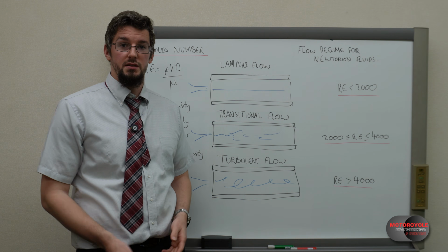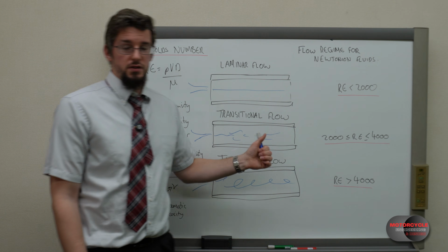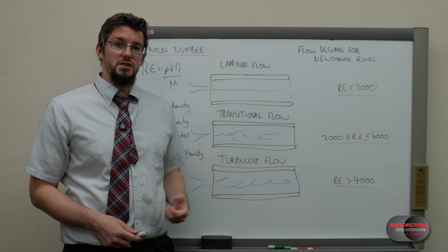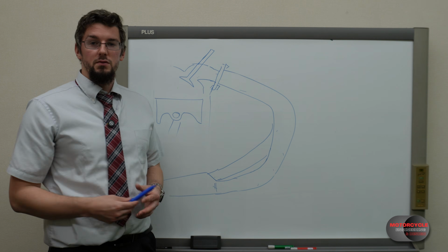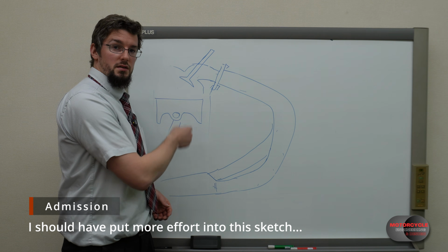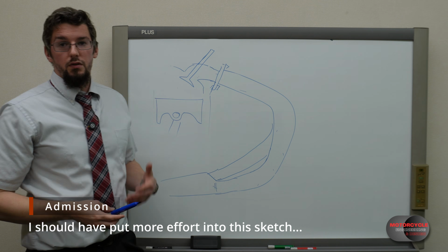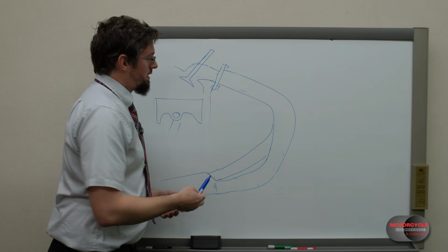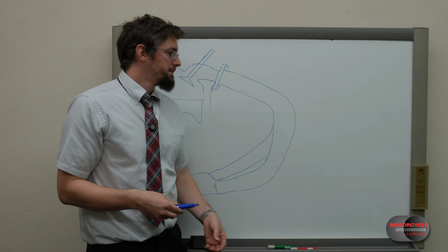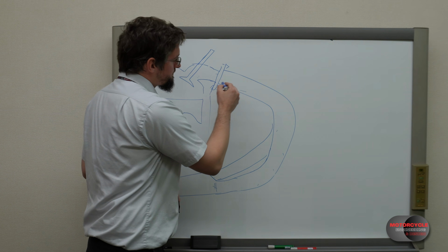So why do we care about this? Essentially, this is our exhaust pipe. Any excessive back pressure that's created from the friction loss is going to be applied to the chamber, preventing the exhaust gases from discharging. So what's actually happening in our exhaust system? Since we actually have a reciprocating piston here, and we have this valve which is also opening every 2 rotations of the crankshaft, we have an intermittent discharge of exhaust gases. It's not continuous. This results in a kind of pulsing nature of the exhaust.